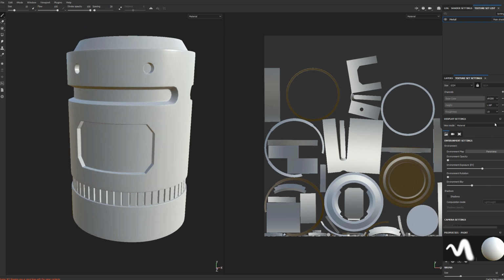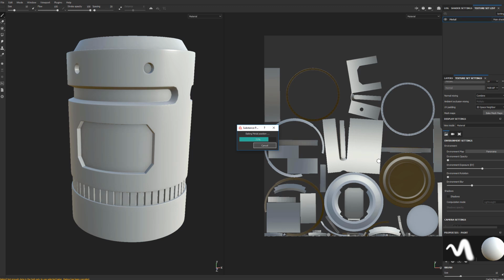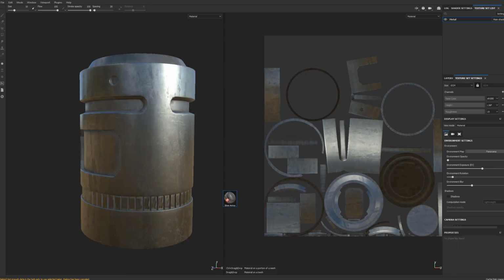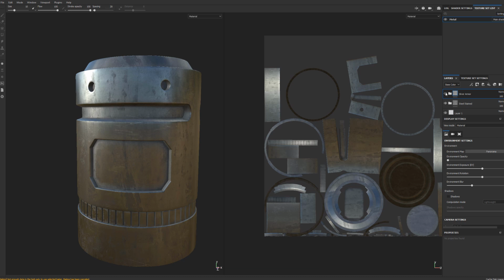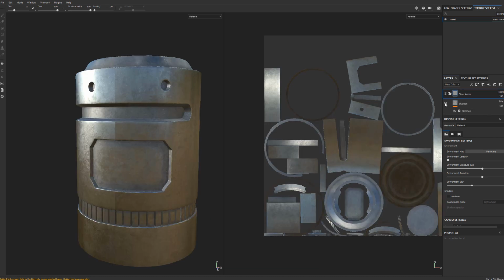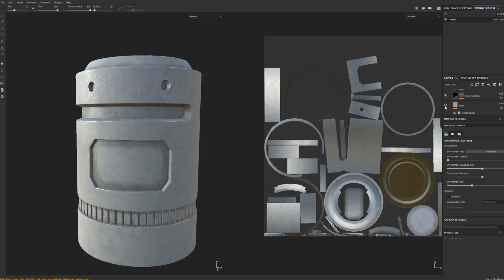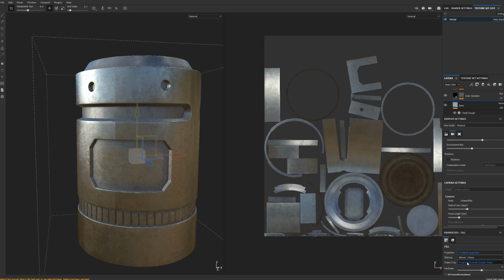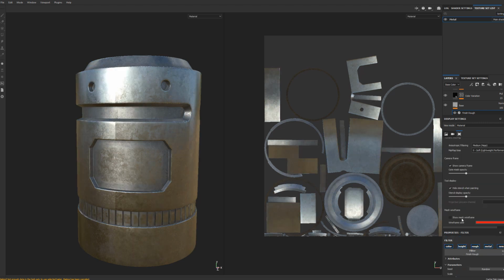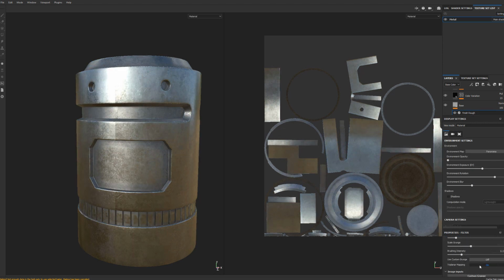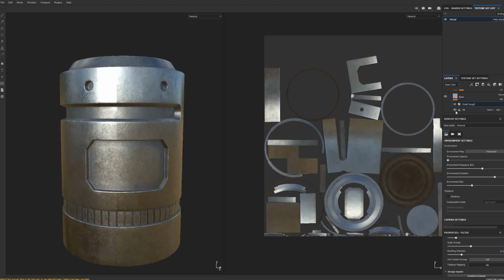So I took my mesh into Substance Painter, and you could obviously see the horrific UV layout here on the right hand side. I just quickly baked out the maps. Obviously for this, since the UVs are pretty much trash, you will have to go to something like a 4K to get decent resolution, since nothing's really optimized and you are wasting a lot of pixels with a sloppy UV layout like this. So I baked up all the maps. Threw a smart material on there, played with the settings a little bit since the seams were everywhere. I tried to minimize some of those seams as best as I could.